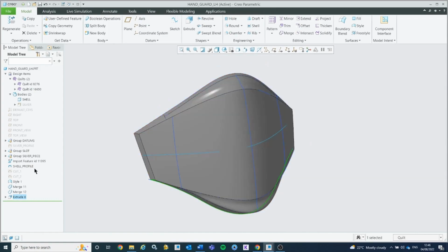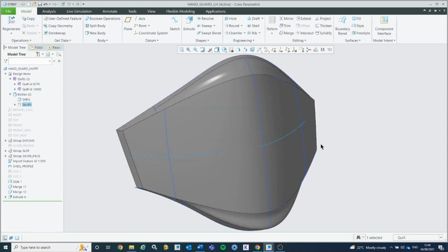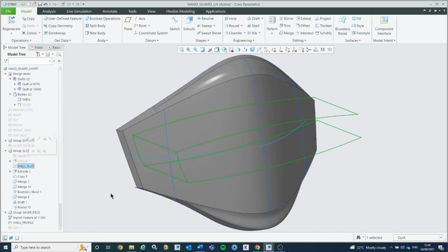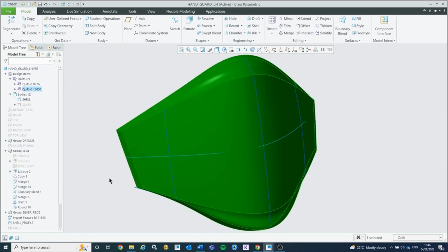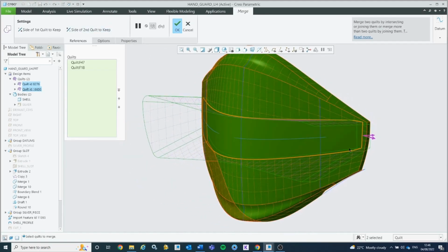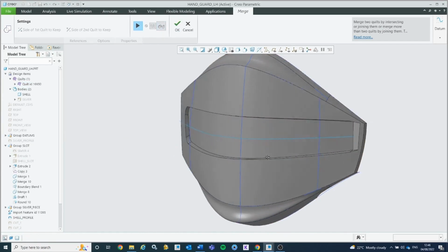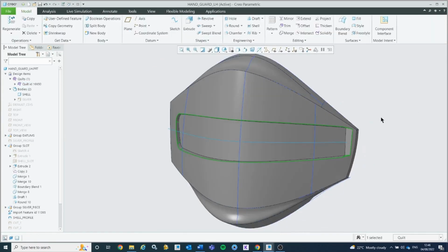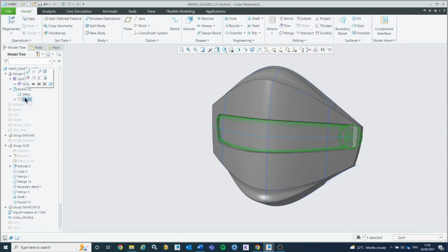So because we've got this extra body here, which is a little accent, we need to make some sort of slot cut out for that. So what we can do is select one slot in here. We can merge those together, and if we flip the direction, we get something that's created looking like this. So now if I activate the slot, it should fit nicely into that section.